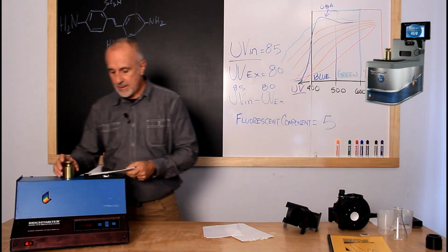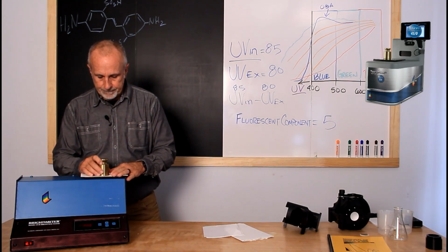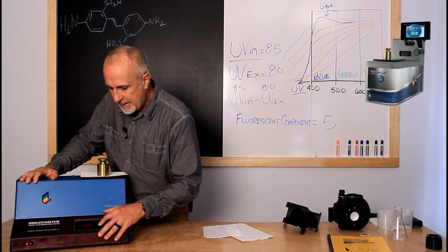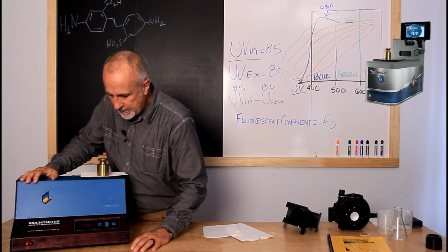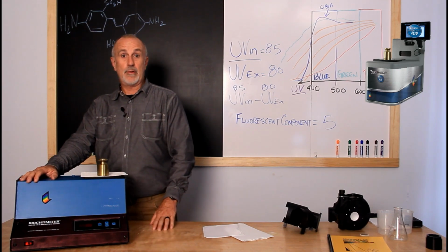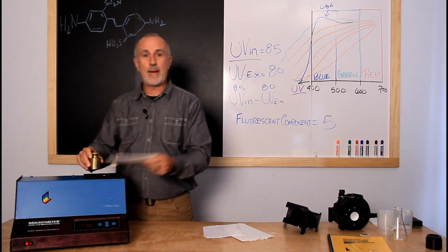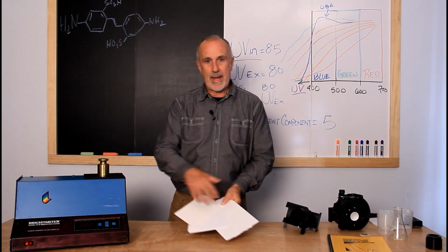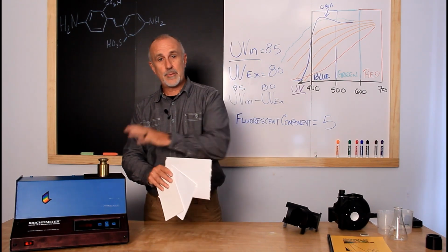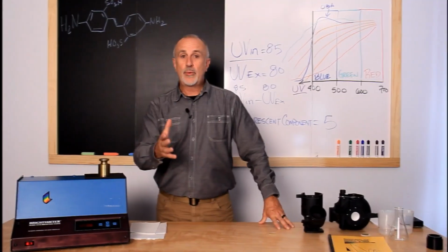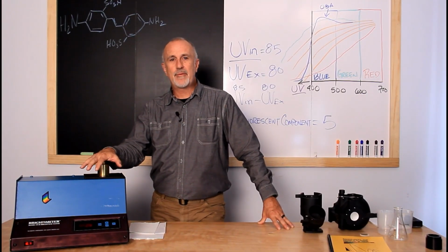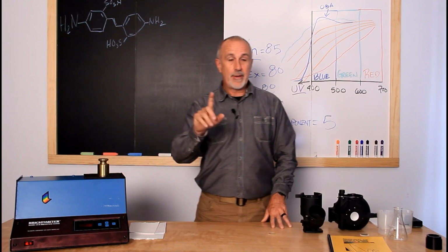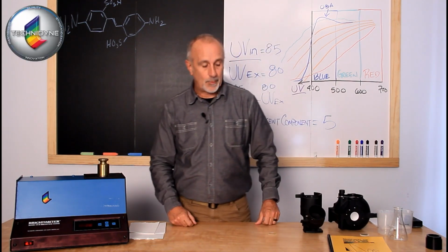Let's take a look at this. This is a pulp pad. Okay, so its base brightness is 79.5, and I do the fluorescence measurement, and the component value is 0, because there are no optical brighteners present in this pulp. So again, depending upon how your dosage is, the instrument's going to read that differently. So again, the TAPPI method for evaluating the effect of optical brighteners is a pretty simple test, but a very important test to manage your optical brighteners.